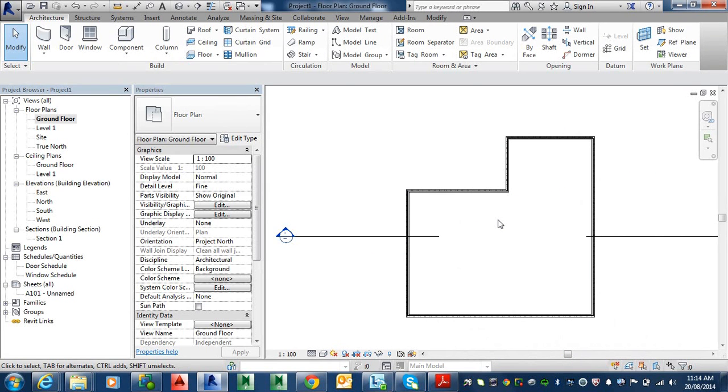So what we need to do next is just have a look at what we've done in 3D. Now, if you look at all the exercises that you'll be given, probably most of them will say go to the 3D view, which is in here. These things here are called views, by the way, in the project browser. This is your project browser, which is where you navigate around the project. There isn't a 3D view in here. When you first start a project, there isn't one.